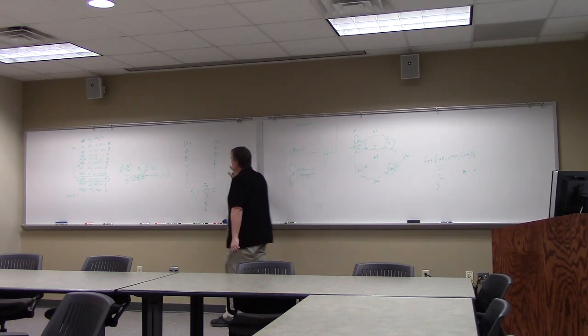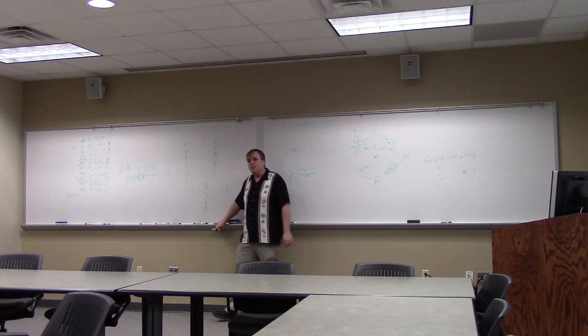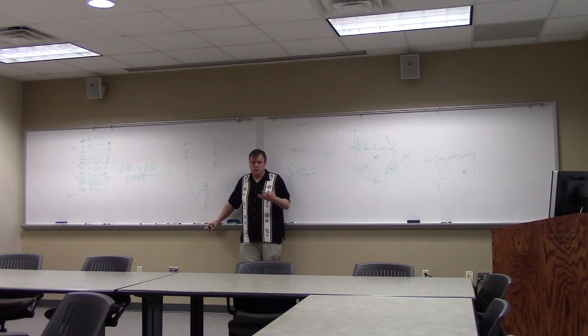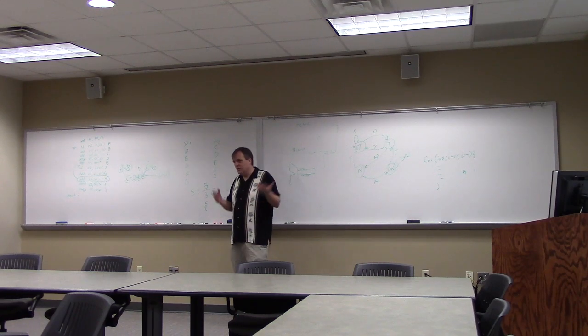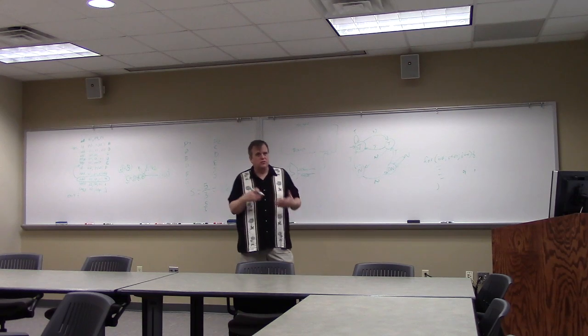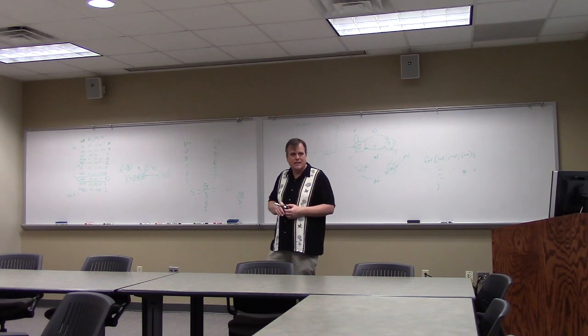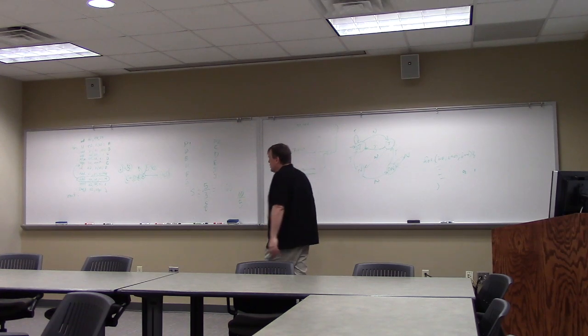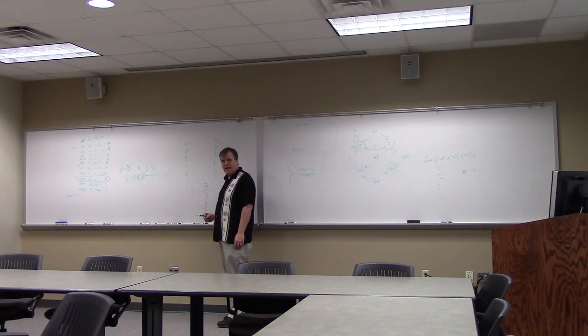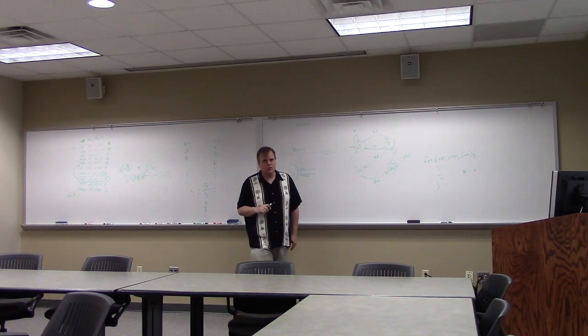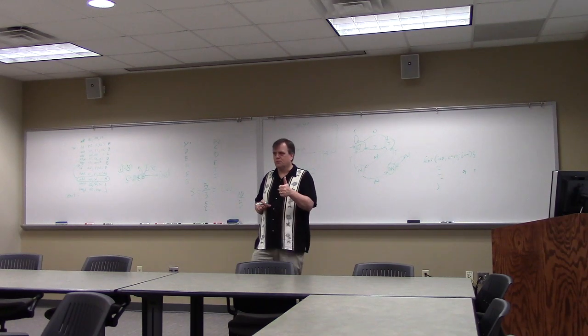And I can obviously give you multiple pipelines, but if I give you multiple memory loads, I've got to increase the bandwidth to your memory, which could potentially be expensive. It might be the only thing that keeps your system alive if you're a very data-hungry application, so that might be necessary. But it's obviously more complicated. So some systems try to do that. Some are completely open, but most people at least restrict you on the branch area, because nobody wants to deal with multiple branches. You know, one says branch, the other says don't.